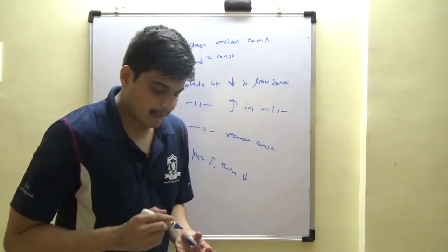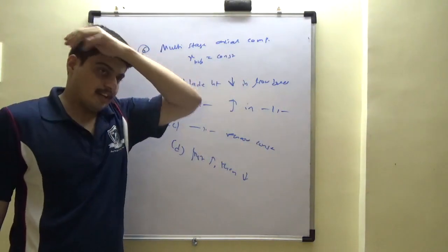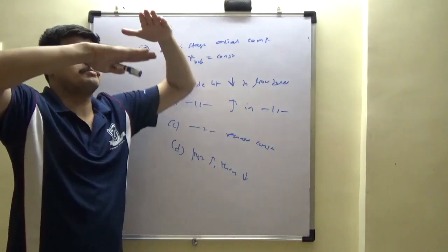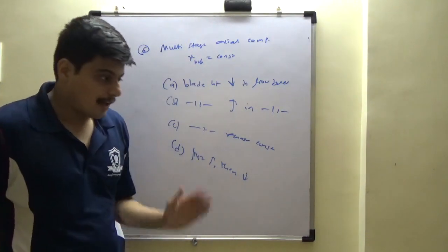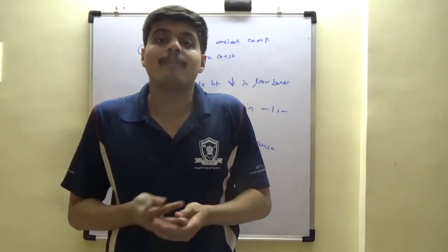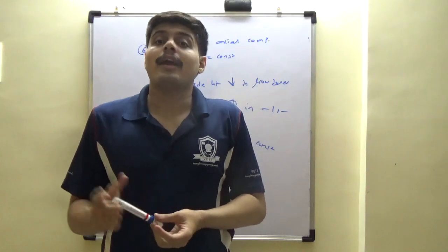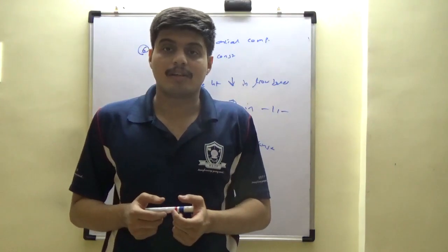If you remember my lecture, we had said you make the hub progressively go up and the clearance between hub and tip smaller, smaller, smaller, because as the pressure keeps building up, density moves up. In rho A V, V is almost similar, relative velocity is not changing much.